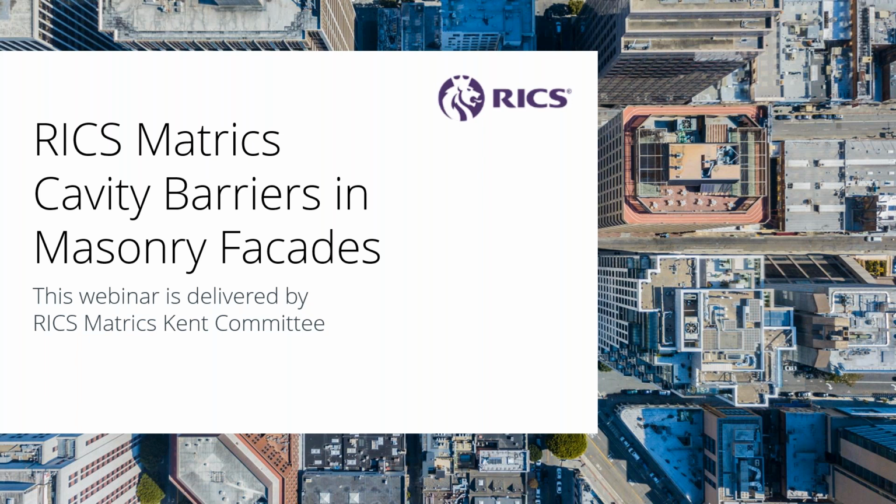Sorry. Next one, what materials are used in our barriers? As we mentioned before, it's a mineral wool base product for our core material. And the next one is, do you use a combination of your barriers with intumescents? Our core material stays the same. We only use an intumescent on our EWI product, and our RH products are the only ones that have the intumescent strip on the front.